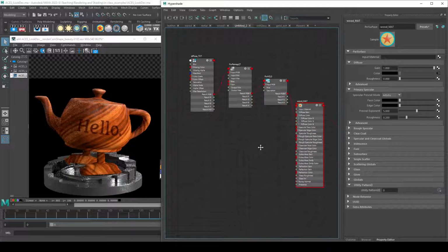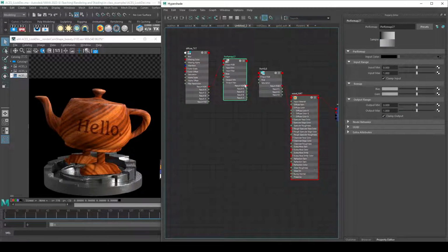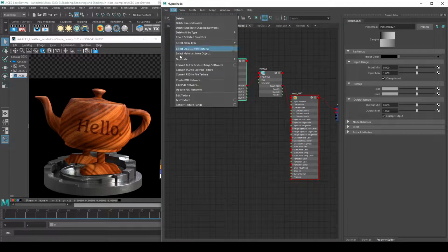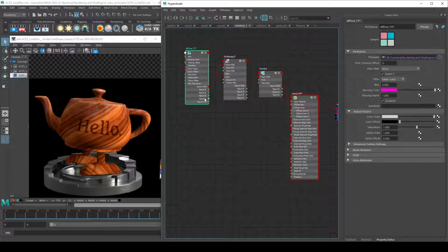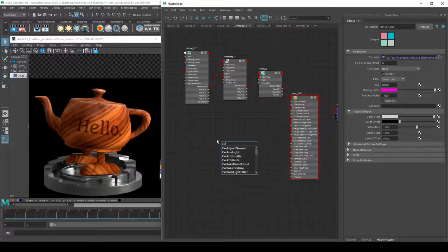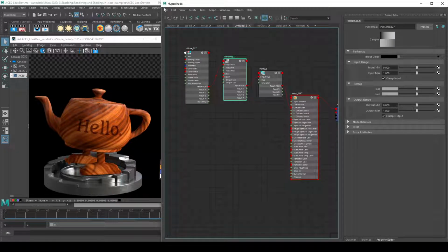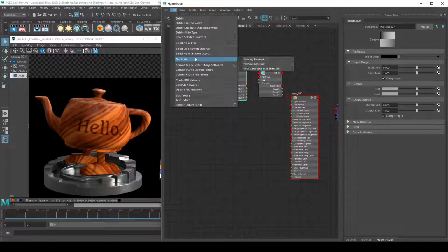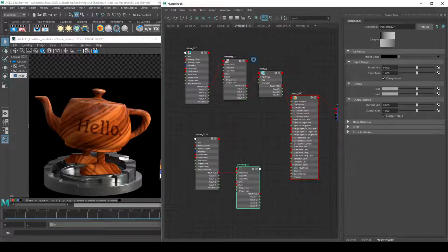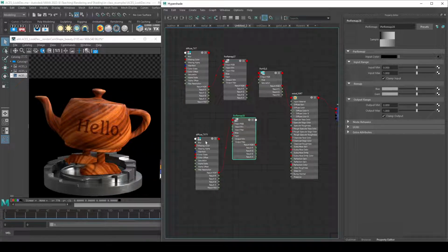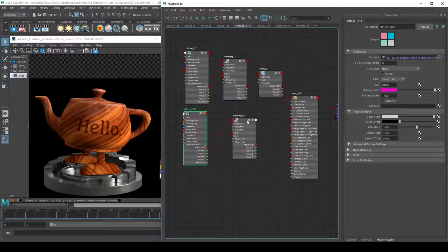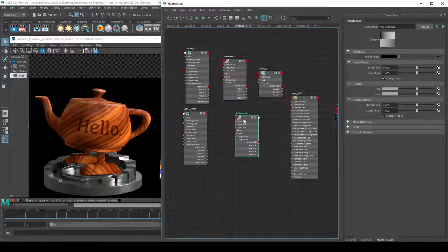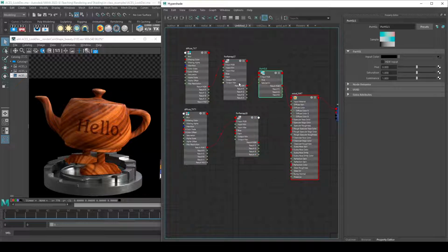Okay, we'll load in a new texture map. So what I'm going to do is I'm actually going to take this Pixar remap right here, and I'm going to go ahead and edit. I could just take this and duplicate it. I can drop in a new one by adding a new node. But I'm going to go ahead and duplicate this remap node. So I'm going to go duplicate shading network. What it's going to do is it's going to take that node and the node that's connected to it and duplicate them with the connections intact. And so if I did that from the HSL, it'd duplicate the remap and the diffuse or the Pixar texture, and they'd keep them connected.